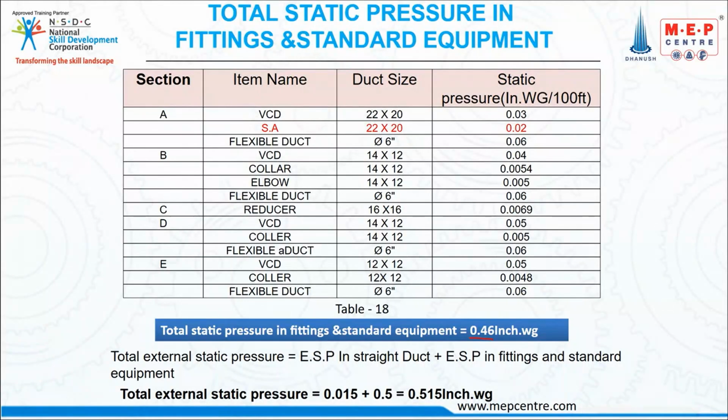So, this is the static pressure in standard equipment. Therefore, total static pressure equals ESP in standard straight duct plus ESP in standard equipment.